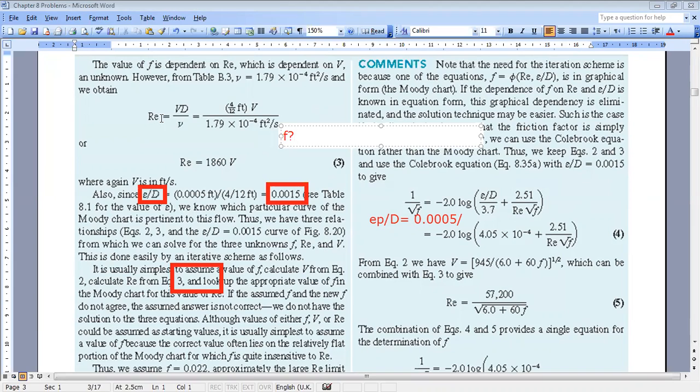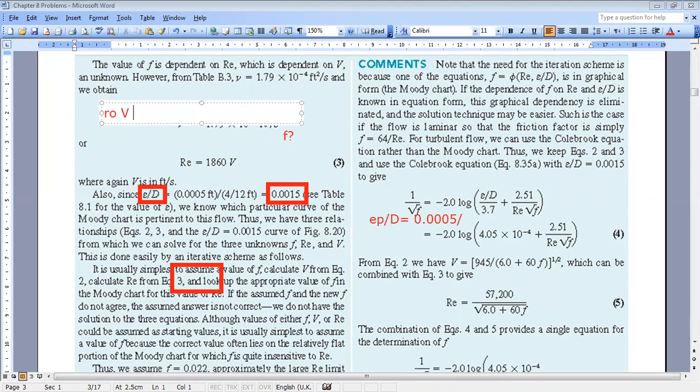The Reynolds number by definition, if I have a circular pipe, a circular duct, the characteristic length will be d, the diameter. So Reynolds is, you are familiar with the formula, rho v d over mu, but rho over mu, you can replace it by the kinematic viscosity. So this is the kinematic viscosity here. And since you have water, you should look at the kinematic.